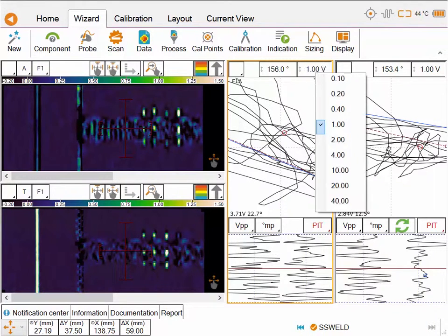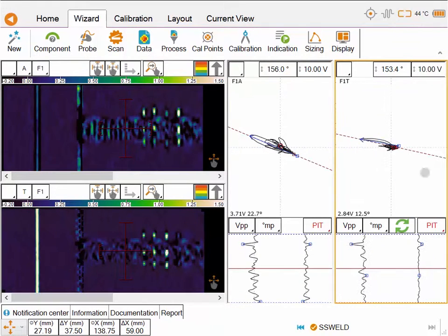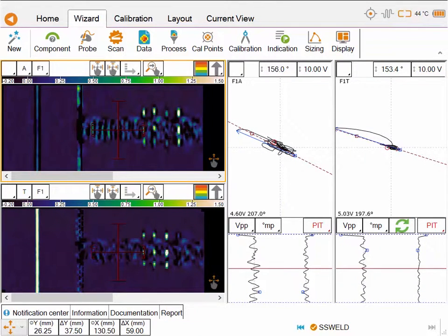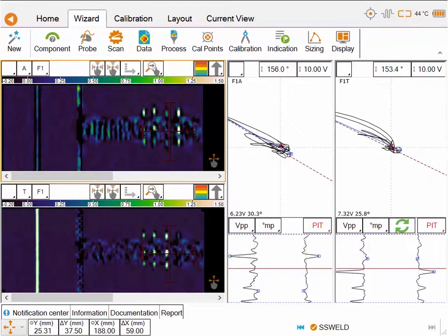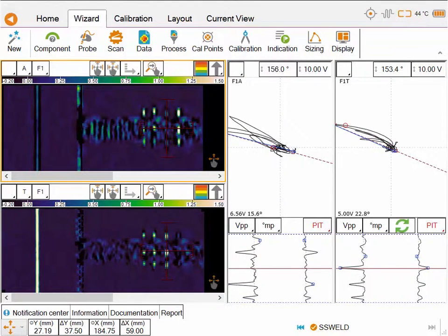I will just change the scale of the display here. So the strong white color that was right in the middle of the scan before, where the weld is placed, is now centered on the null mark, and the signal looks much smaller, and I can detect the cracks that are on top of the weld quite easily. Without such a filter, it's very difficult to see the defect located in the weld.